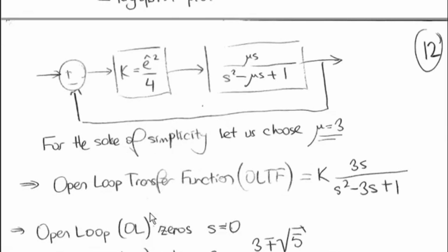In the case of our example, we have this picture here. In this case, although the describing function was a complex one, we could get rid of that complex gain by putting this S here. So therefore, the gain at the end is a real and positive quantity. So therefore, what we can do here is use the root locus plot to determine the stability of the oscillations.